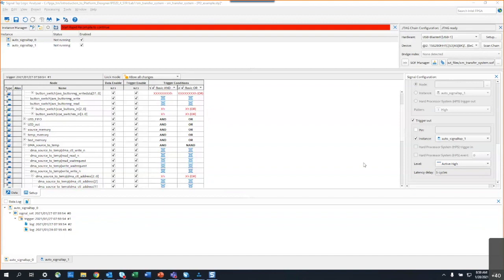because the lesson I want to give to you is that if you want to use signal tap, like other planning, it should be a part of your planning of your FPGA design, because if you do not have space in your device, you're not going to be able to add signal tap later on. So plan for signal tap, think about the resource usage, and like I said, I wish it had the estimate here. I should find out about when that's coming back into Pro, but being able to know how much resources it's going to use is important as well. So plan your use of signal tap for some point in the future, because chances are you will want to use it.